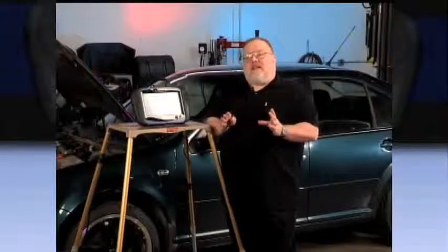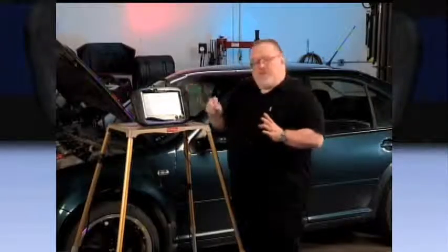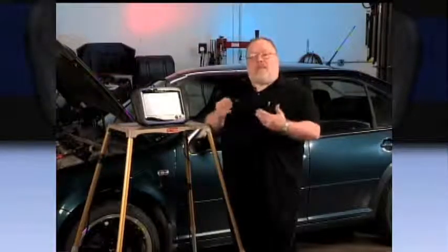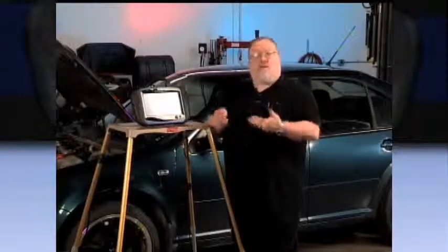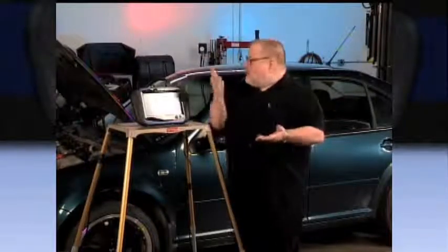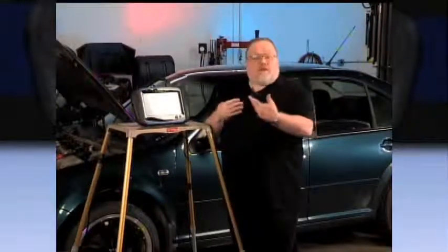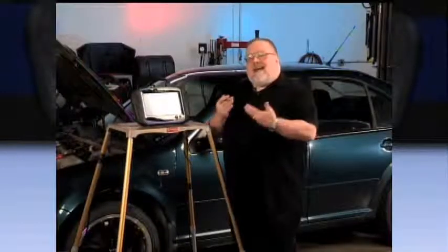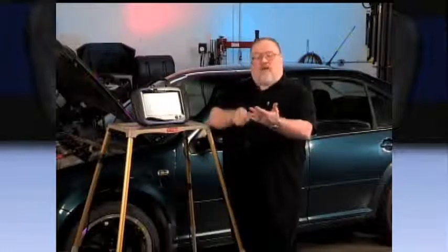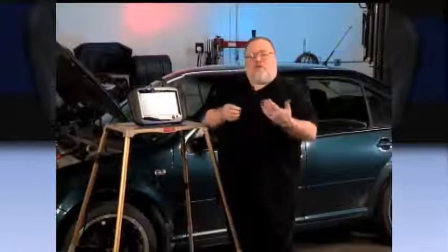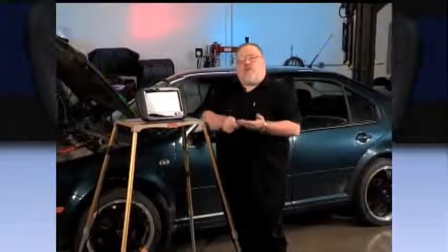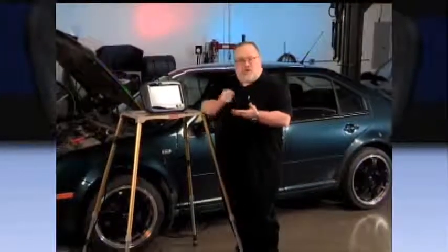But the point being is, I've got the information at my fingertips as to what the computer wants to see driving down the road and what I'm actually getting. What we're looking for, of course, is for those numbers to match up. Now, in this particular vehicle, this is what's known as a low pressure turbo. It's a 1 atmosphere turbo. So when you're looking at data off the turbo, it's going to show you not only the atmospheric pressure, which is going to be approximately 1,000 millibar, but the boost above atmospheric. So it's always absolute boost or absolute turbo pressure.